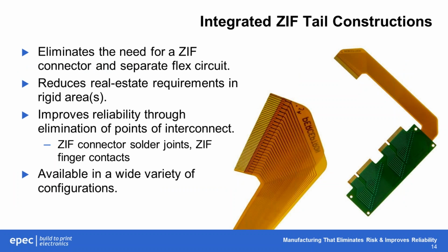Another common one, and this is probably of the more advanced rigid flex constructions, this is probably the most common one that we see, and that's where a ZIF tail is integrated into the rigid flex. So this in turn eliminates the need for the ZIF connector to be mounted onto the rigid board, eliminates the need to have a separate flex circuit.